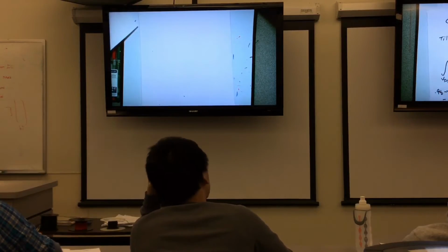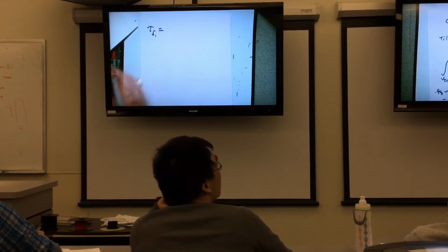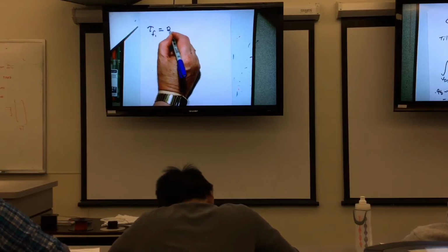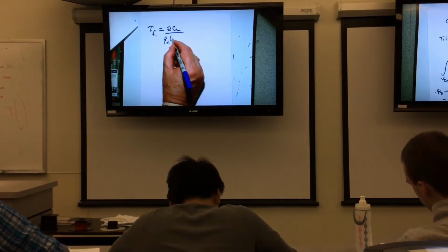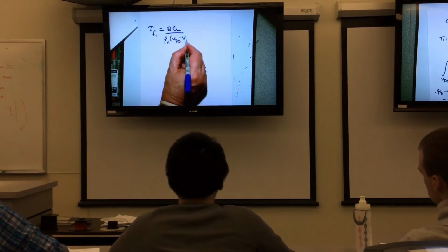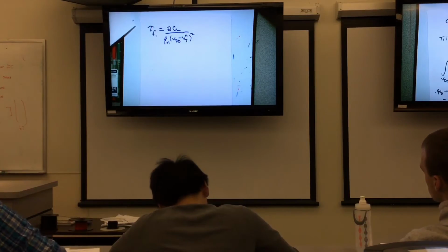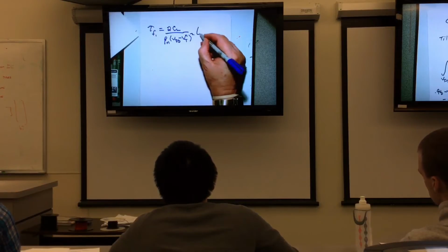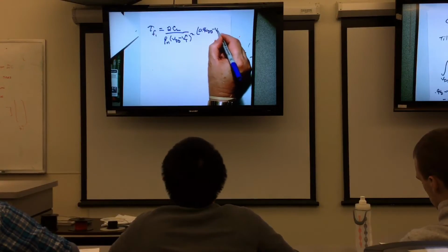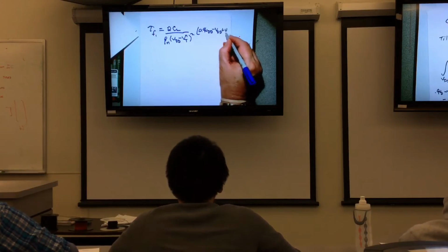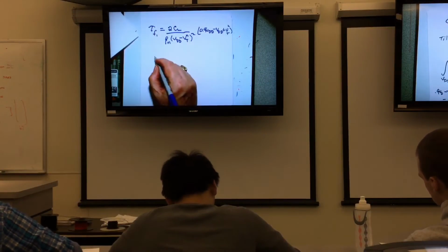And this tau fall 1 would then be equal to 2 times C sub L divided by beta n, and this is all constants down here, times this 0.9 VDD minus VDD plus the threshold for the n. Okay.